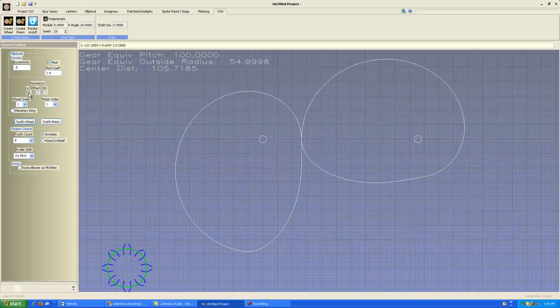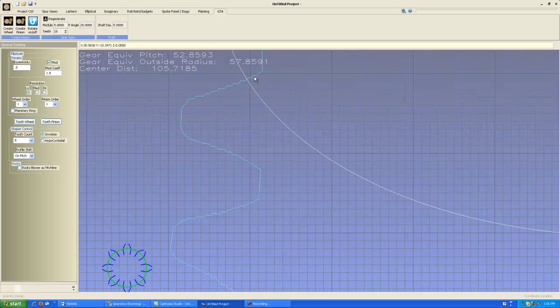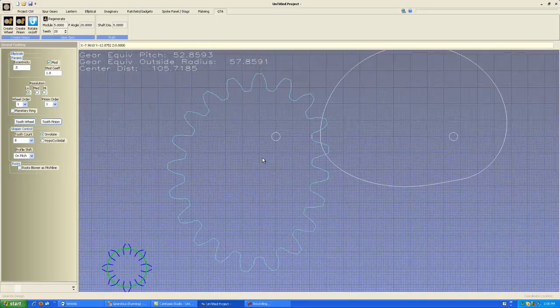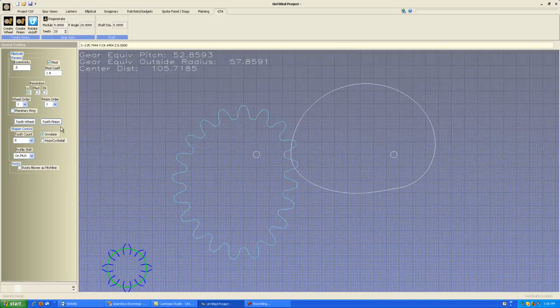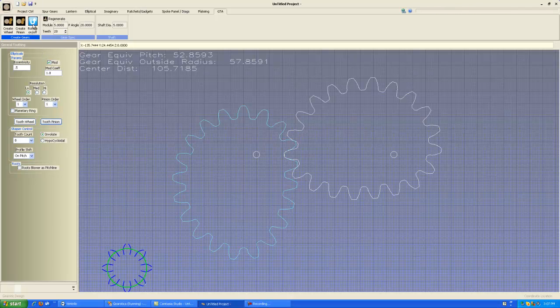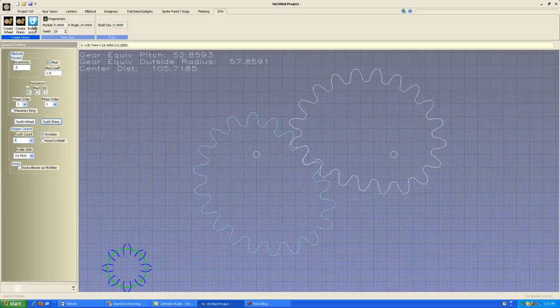Let's switch to low resolution and tooth the same one so you can see the difference on the involute cutters. Still a pretty good job, although we're getting jerkiness and roughness in the teeth. I wouldn't try cutting them from low res. I would probably only cut on the high res option. We can tooth the pinion. And you can see that these gears would rotate together quite well.